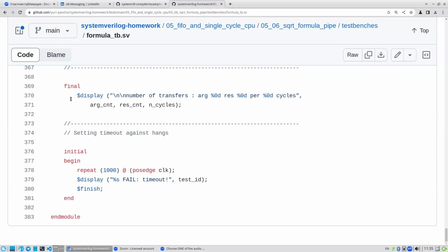You can see that even without a formal example, we have some examples running on an FPGA board, and maybe we can create a demo where you have RTL running on an FPGA board, and then it talks with the SystemVerilog simulator, and we can use either Icarus Verilog and the GPI interface, or we can use cocotb.